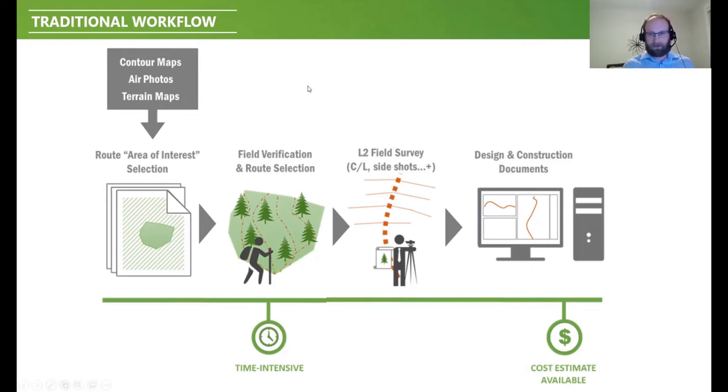With this, your surveyed surface is only going to be as wide as the data you collect. So usually you'll get 50 feet or so either side of center line, and that's all you have. So when you go to actually do the design, that's your footprint that you're stuck designing on. You can move the alignment either way, but you can only go so far.